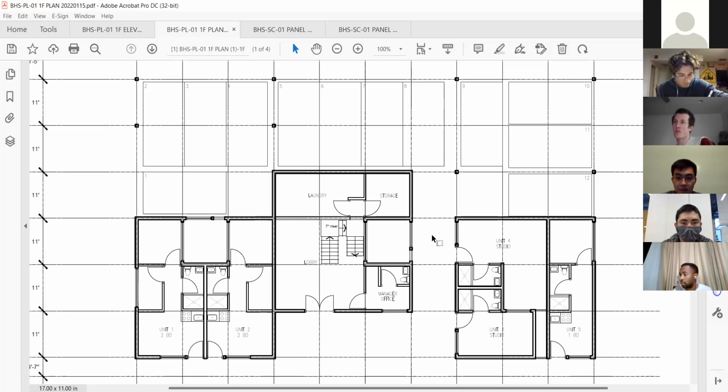One thing I was just thinking is that maybe we could make an area in the Miro doc. I just put a board to the right of the plans where we could put some of the proposed construction assemblies, the details of the different types in the project. I know that's going to be an ongoing thing, but if we throw up some general details, like what the 2x6 wall assembly is going to be, what the waterproof deck assembly and the top roof assembly are going to be, just finding details of existing designs, that will give us something to go off of. Then the engineer team can say this needs to be bigger or smaller or different, but they have a baseline.